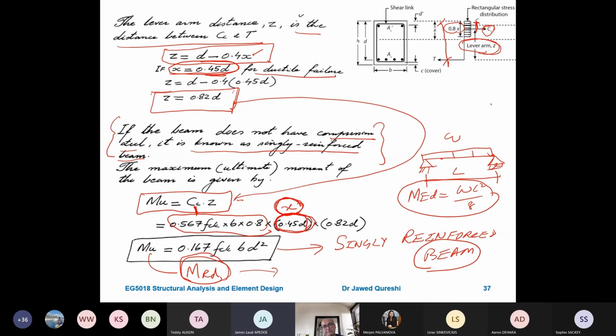What is the limitation of just increasing your tension bars? Couldn't you just make the steel bars that are in tension a higher diameter, make the area bigger? You can make the diameter bigger, but it has to be balanced by the compressive side. If the tension force is really high and the compression is really low, it's not going to be balanced, is it?